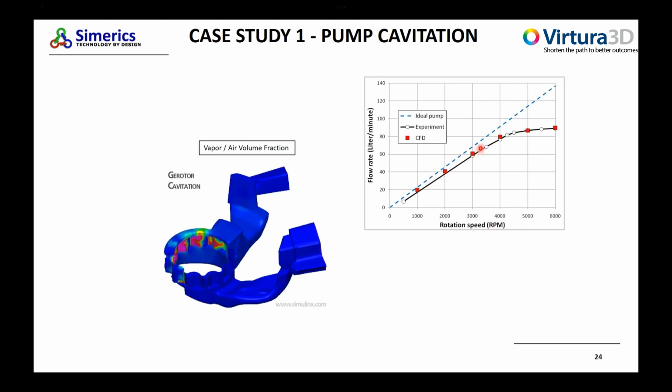And you can see we can capture that leakage effect inside the pump. At the inception of cavitation, you'll start to move away from the linearity. Then that's when it starts to plateau, and we can capture that in this case as well.